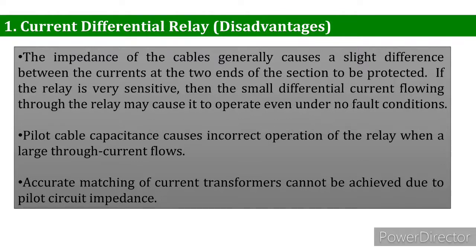The second one is that the pilot cable capacitance causes incorrect operation of the relay when a large through current flows. The pilot cable, first we have to define that. Pilot cables are basically used for control, protection, signaling, telecommunication and data transmission purposes.